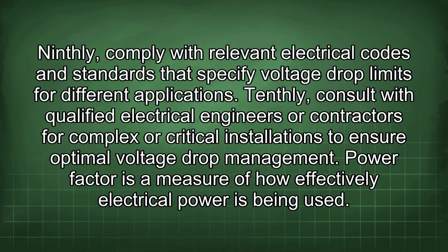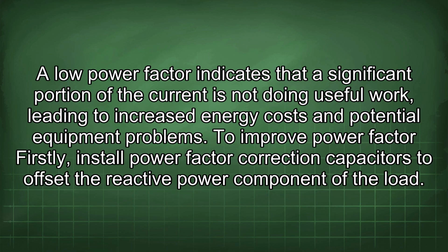Power factor is a measure of how effectively electrical power is being used. A low power factor indicates that a significant portion of the current is not doing useful work, leading to increased energy costs and potential equipment problems. To improve power factor, firstly, install power factor correction capacitors to offset the reactive power component of the load.